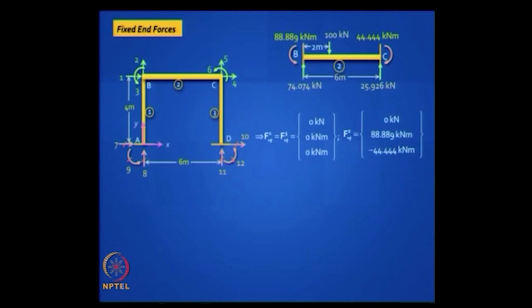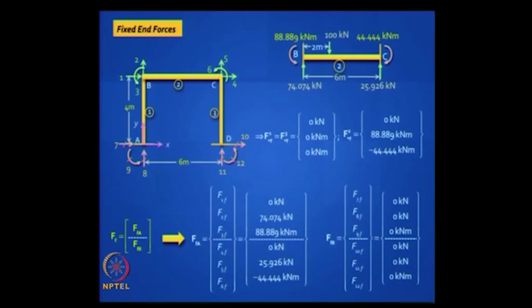Now we take this element alone that has non-zero fixed end force vectors, and when you want to put it onto that structure, you have to do it by inspection. This is a shortcut method. Reduced element stiffness method, you can't do TD transpose and get it. So doesn't it make sense to write down your fixed end force vector like this, because what are the contributions from the 3 elements?